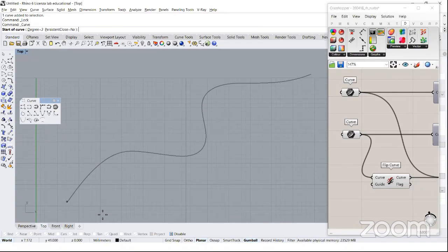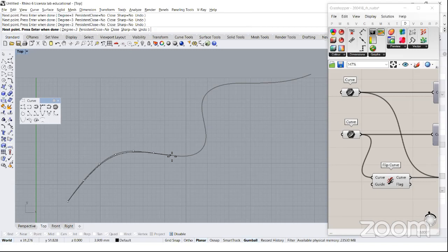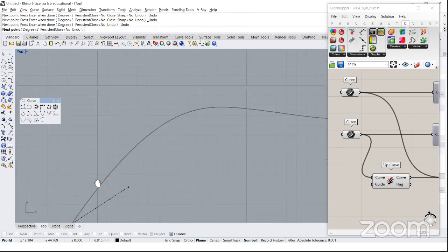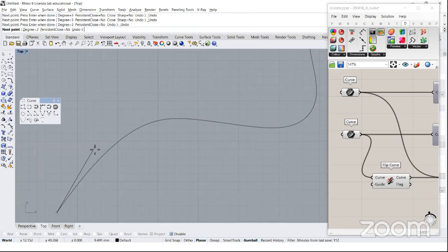So for example, if I see that this line starts from here, and I need to place other control points, I don't place control points on the path, because I know that if I do this, my curve will lie inside the original curve. So there is this kind of deviation. But once I know how it works, and I'm expert enough, I tend to place the control points in the outer part. You see, because when I bend the next point, I go closer to the original line. So once you are expert enough, you can start placing control points, and this naturally leads to a better position of control points.